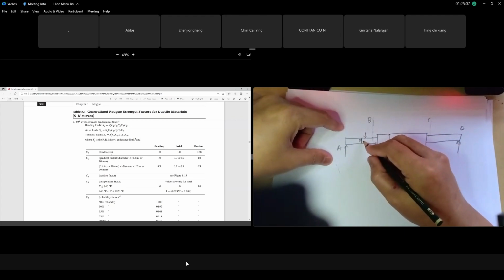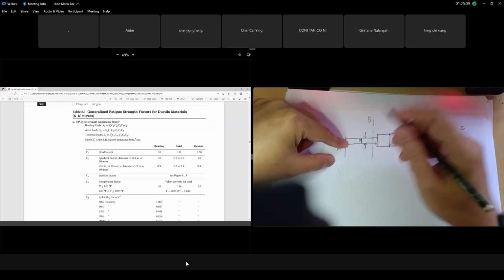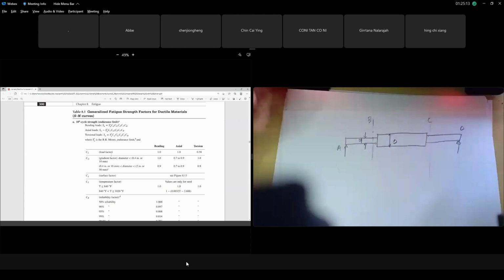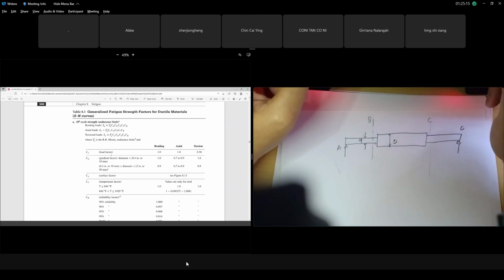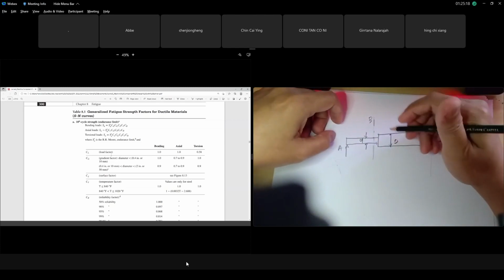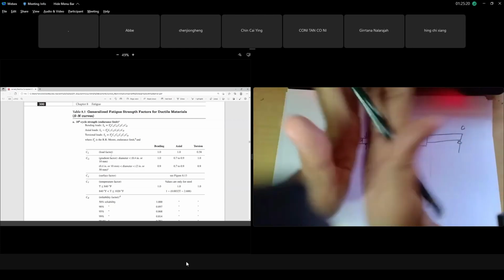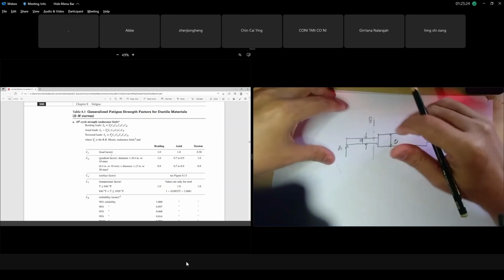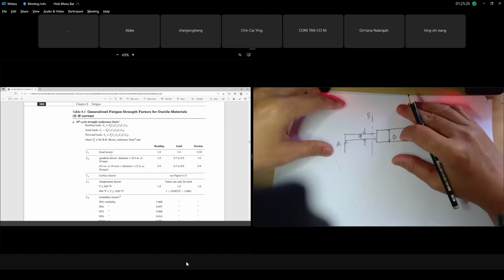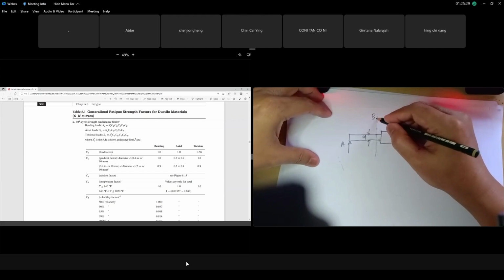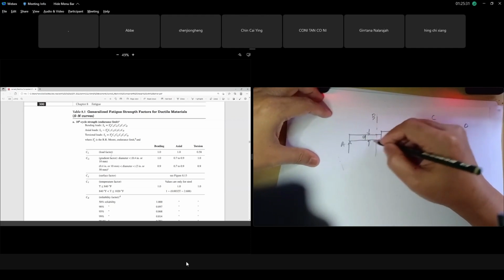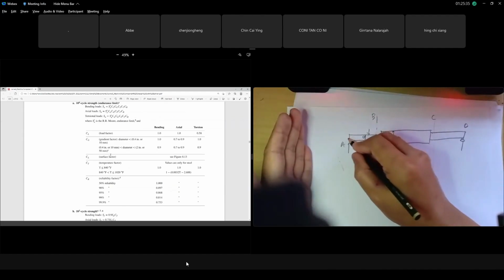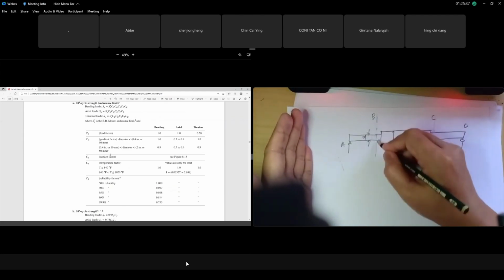Normally in your previous assignment, your shaft was just a plain diameter, right? But normally in practice it is always stepped. Because we mount the pulley, there will be a step at the shoulder, so the gear will be blocked by the step and will not go out of alignment. Because we have a smaller diameter and a bigger diameter, we go for the smaller diameter.